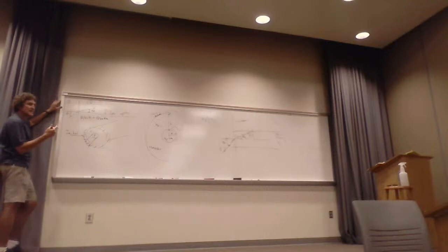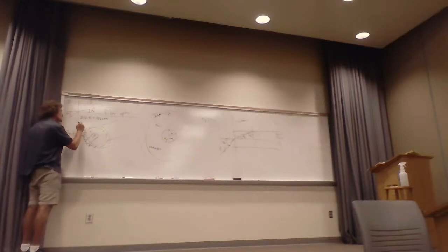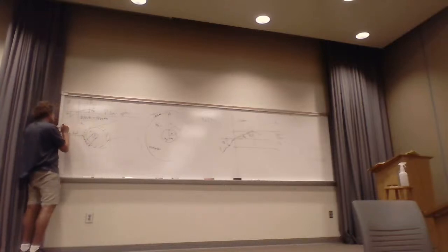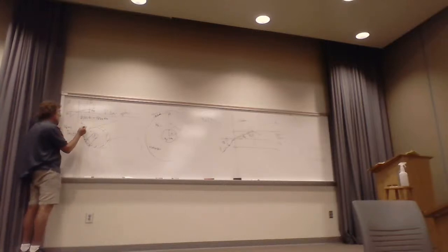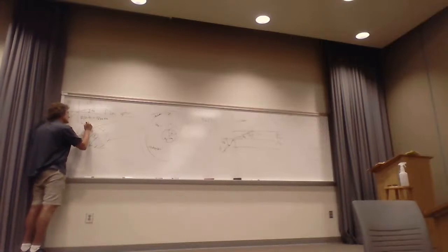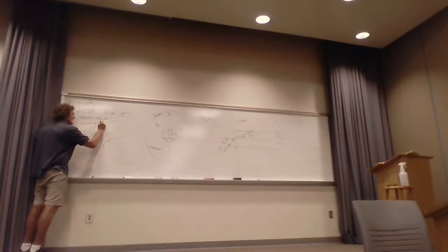Well, beta is omega times the square root of mu epsilon, and ultimately with all the cancellations, you can prove that, assuming mu relative is equal to 1, n1, the index of refraction in region 1, times the sine of the incident angle is equal to n2 times the sine of the transmit angle.